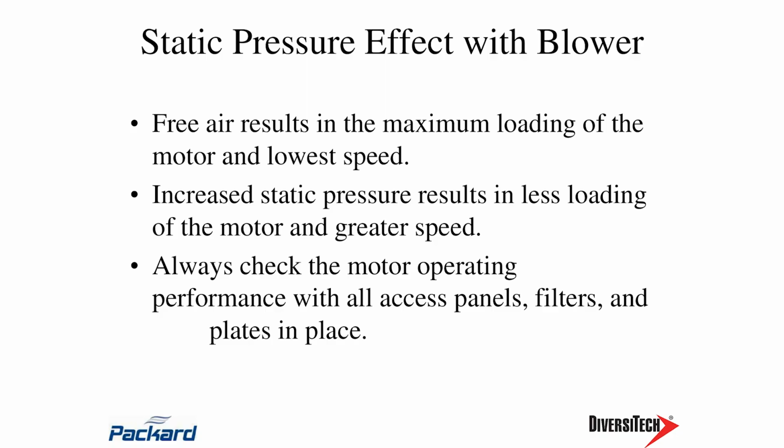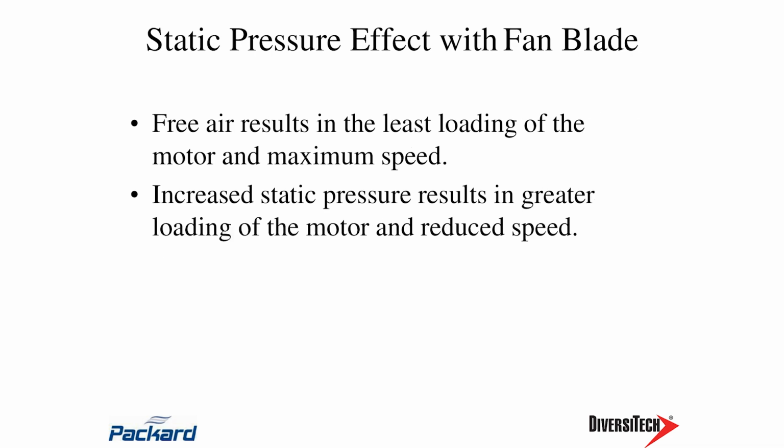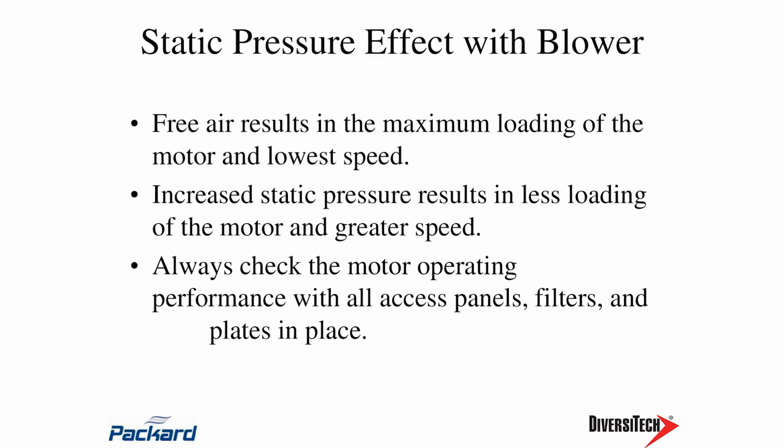So now when we look at blowers versus fans, the static pressure affects it differently, in just the opposite manner. So with blowers, free air is the maximum loading, and my amps are going to be high at that point. But as I add static, it restricts air. It restricts the number of those boxes of air that blower is working, and less air then takes load off of that. And my amps will drop. The speed will increase with that.